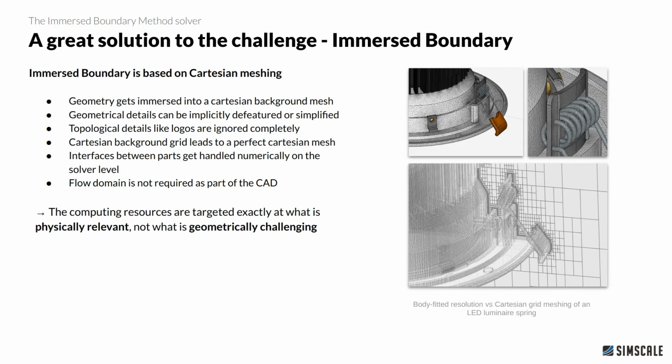Another advantage of the method is that you can use flow domains as part of the CAD, but you can also leave them out and just essentially cap internal flow regions with cap surfaces, or you can put a simple primitive box around your model if you have an external flow problem and run with it. So you don't need to do any Boolean CAD operations, and you don't require the quality in the CAD that it needs to do these kinds of operations.